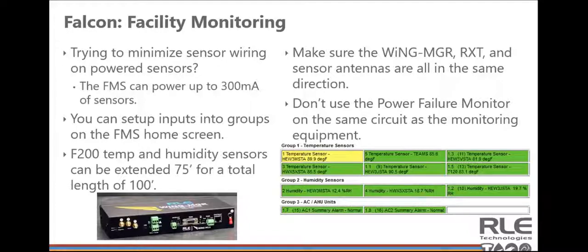And we put the schedule on there because it's great for those items that you're only using maybe once or twice a month, but you still need to run intermittently. A pump in a chiller plant or a chiller itself. If those devices are legacy pieces of equipment and they don't have an automated schedule to turn them on, spin them up for 15, 20 minutes once a month or so, having a relay to do that has been quite beneficial to some of our customers.